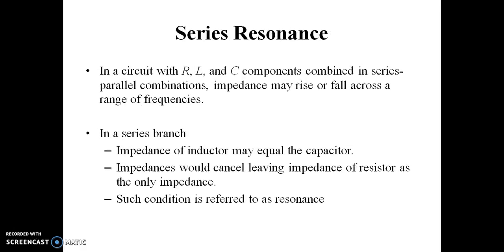Series resonance. In a circuit with R, L and C components combined in series parallel combination, impedance may rise or fall across a range of frequencies. In a series branch, the impedance of an inductor may equal that of the capacitor. In that case, the impedances would cancel, leaving the impedance of the resistor as the only impedance. Such a condition is referred to as resonance.